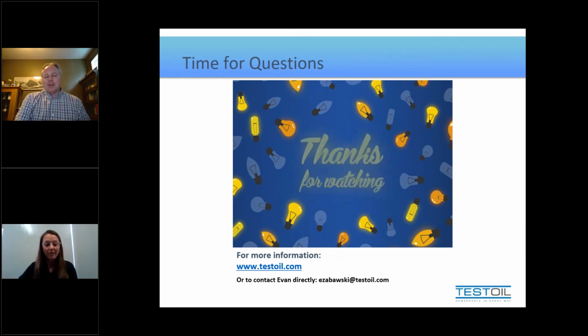Well, there's a slight relationship to that. Obviously, the smaller the micron rating, the more of a restriction you could expect. However, like I said, we can balance that by making the pleats deeper and adding more density to the pleats to increase the surface area, so that even though the holes are smaller, we simply have more of them. So the overall surface area of flow through the filter, we can balance to a point when it comes to filter design.